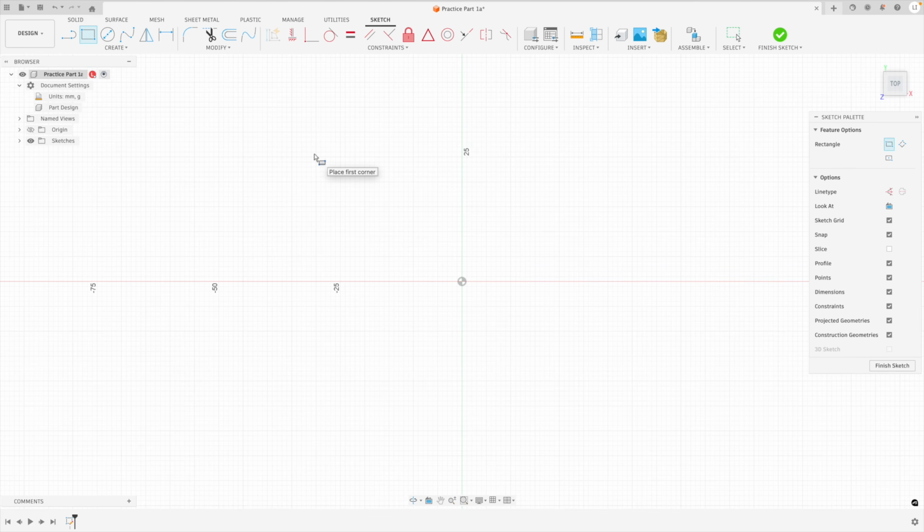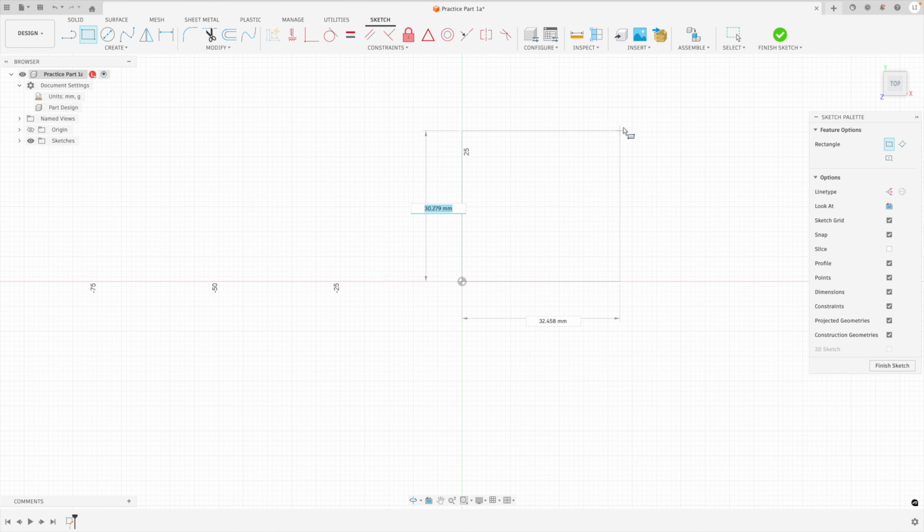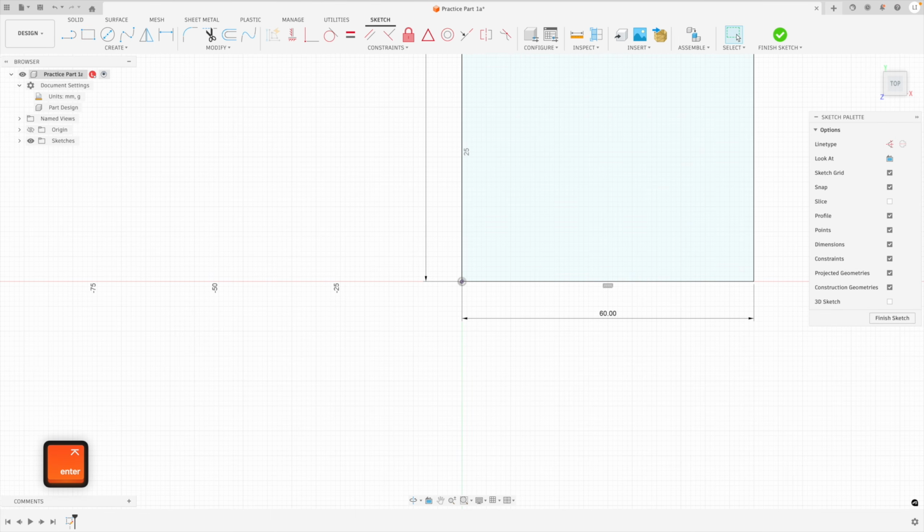Let's do the exact same thing as our primitive and select the origin and then move up into what's called the first quadrant, which is the position between 12 and 3 o'clock from our origin point. Now, let's type in our dimensions. Input 100 in our first dimension callout. Then Tab, then 60 in our second dimension callout. And then press Enter to set everything.